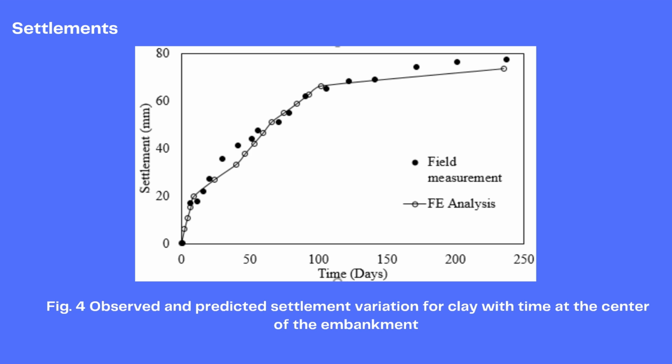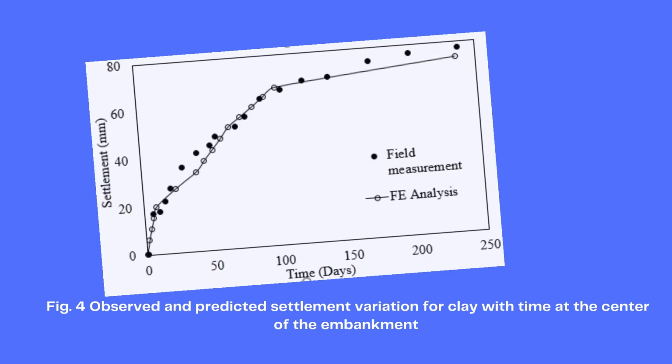And if this embankment is assessed based on this design standard, the total in-service settlements can be a problem after a few years for this embankment. The differential settlements are very low and they are not going to be a problem.